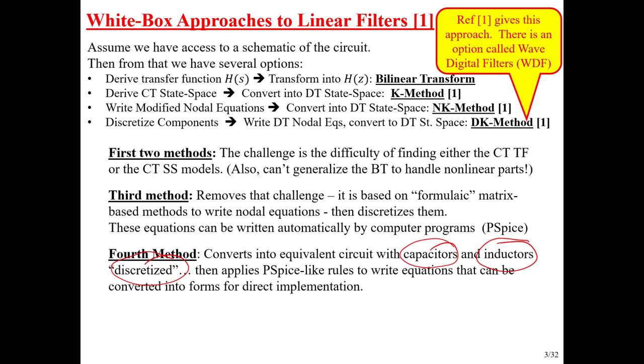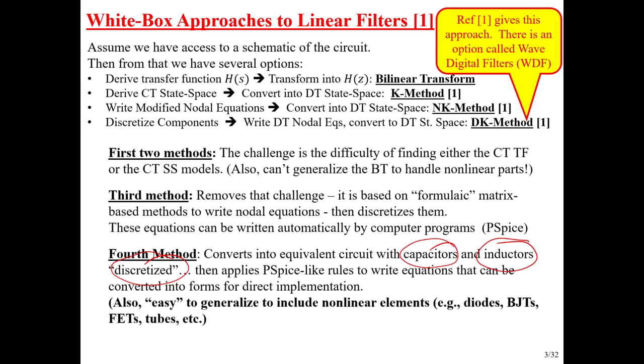And then we can just put those into an effectively discretized model or discretized circuit, and then write modified nodal equations for those. And there is no need to convert to a state space model then, because we've done that effectively for each individual capacitor and inductor. And that turns out to be a very, very nice way to do that.